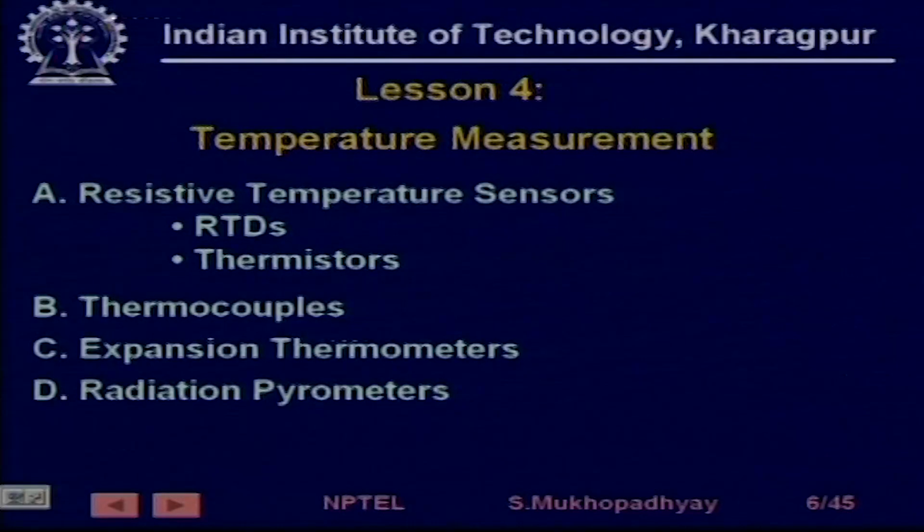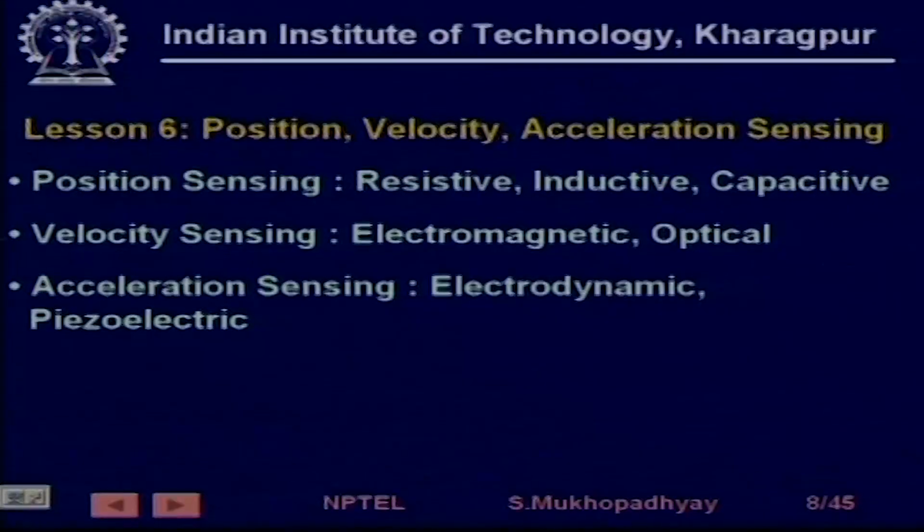Then, having taken a look at an abstract sensor, we started looking at the individual sensors for the typical process variables which are measured and controlled in an industrial environment, like temperature. We talked about various kinds of temperature sensors and, of course, their signal processing circuits. We talked about pressure, force and torque sensors: low pressure, high pressure, force measurement, strain gauges, torque measurement.